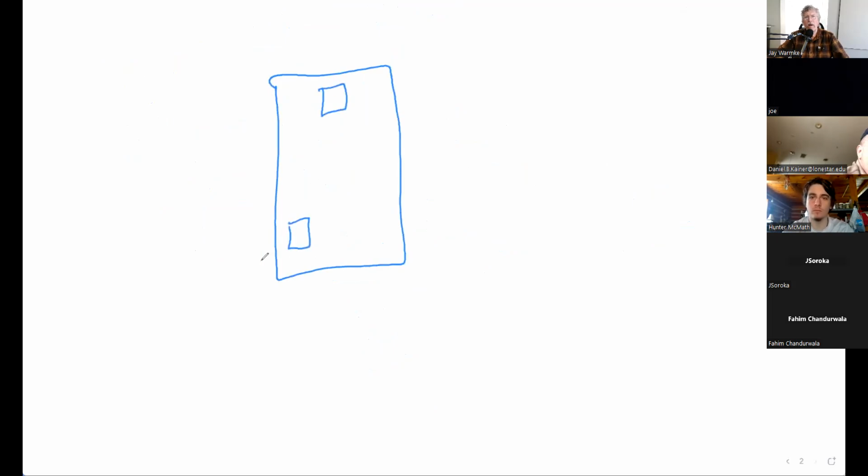Okay, so I'm coming into my service panel. Here's my main. Here's where I want to hook up. The first thing you need to know is in a service panel, you always want to locate your solar array's input as far away from the main as you possibly can. Normally, your main's going to be up at the top, so you want to go down to the lower left or the lower right-hand corner. You want your two inputs on opposite sides of the bus bar.